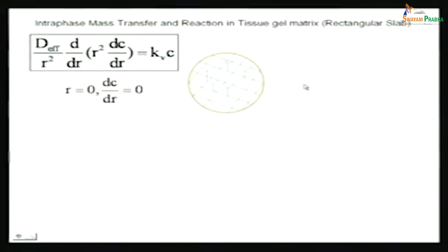I don't think we'll have the time to finish this. So the boundary condition is the symmetric boundary condition, because we've assumed symmetry: at r equals 0, dC/dr equals 0. Fine. What will be the other boundary condition? Straightforward: on the surface the concentration is given by K C0. So the surface is given by r equals R. So how do you solve this now?